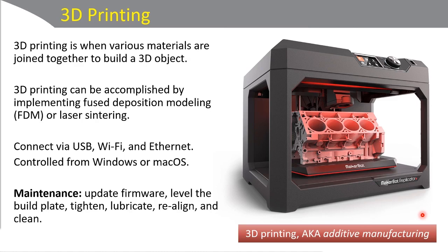Finally, clean the device, including the extruder's drive gear. So we have the extruder here, and that's what actually puts out the filament to build the prototype or whatever you want to build here. And the gears are inside here, so you're going to have to clean those out once in a while. You also want to clean up the build plate, make sure that's clean of any residue, and so on. Clean out the device.